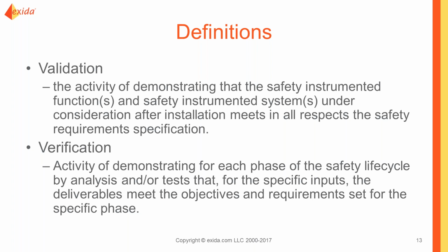So typically, overall, you'll develop a verification and validation plan where phase by phase and step by step you verify that that step is done correctly, and then at the end you verify overall that the system is in the correct configuration and can achieve and perform its safety function.